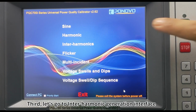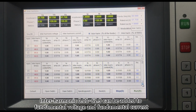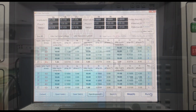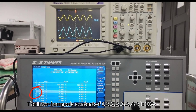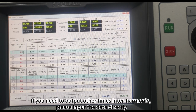Third, let's go to interharmonic generation interface. Interharmonic from 0.01 to 62.9 can be added to fundamental voltage and fundamental current. Select interharmonic 1.5, 2.5, 3.5, 4.5, press run button. The interharmonic content of 1.5, 2.5, 3.5, 4.5 is 10%. If you need to output other times interharmonic, please input the data directly.